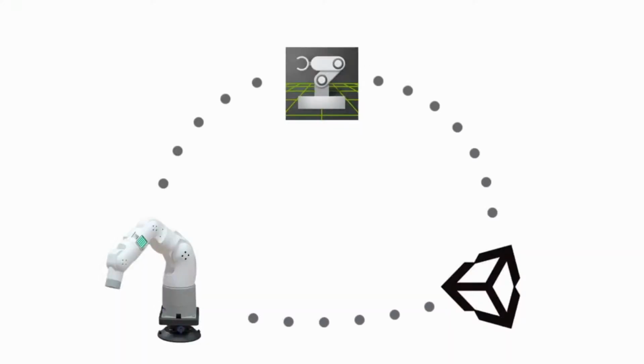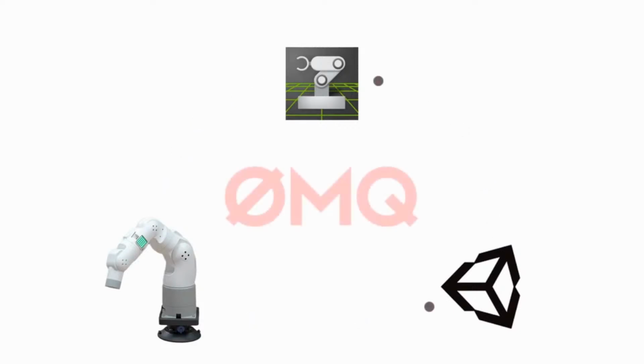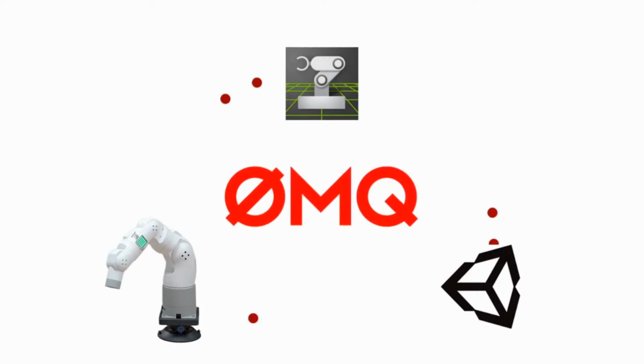A key part of making this digital twin work is the network setup. We've got data constantly flowing between the robotic arm, Isaac Sim, and the VR interface, all in real time. For this, we're using ZeroMQ to send and receive data across the network. By testing different configurations of platforms, we've landed on this combination: NVIDIA Isaac Sim for the robotic simulation, Omniverse and Unity for the VR interface, and ZeroMQ for the networking. It's a pretty powerful setup, but the best part is how smoothly everything works together.